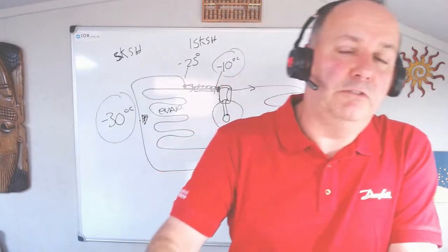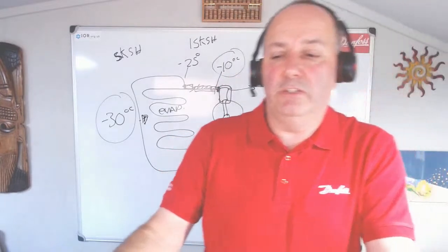What's in the store, what the temperature is, how much temperature increase you can physically have for the product that's within the store. The big freezer rooms that I've worked in over the years, they would generally try and defrost 1 cooler at a time, purely to limit the temperature increase, but also to limit the amount of steam and moisture that's generated from that evaporator that's on defrost.